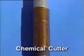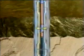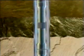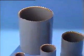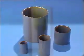It is often necessary to cut a section of pipe or tubing to remove it. Among the cutting tools available to Weatherford wireline operators is the chemical cutter, which uses hydrofluoric acid to cut pipe. The chemical cutter severs the tubing without leaving a flare or debris. This eliminates the need to mill or dress the top of the fish, making it easier to recover with an overshot fishing tool.